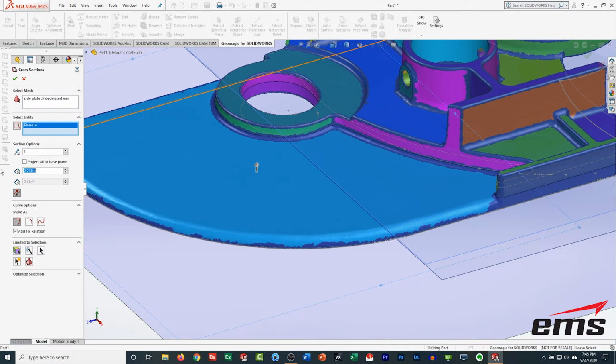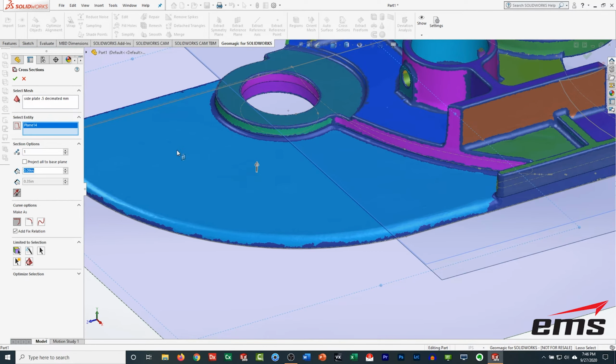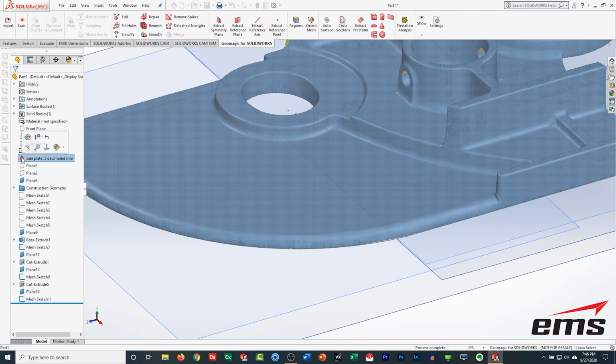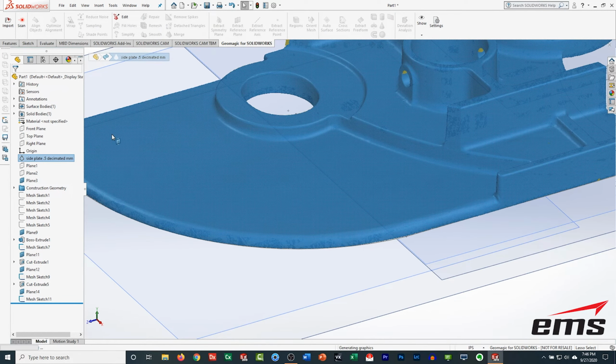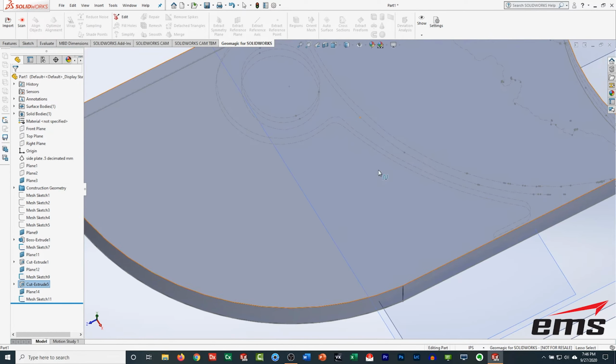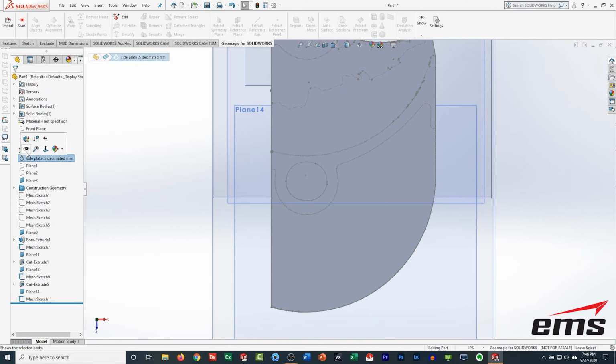We're cutting our section. Again, we want to bump it up. This radius is a little bit bigger, and get it up. You always want to try to get off that radius and get on that vertical wall, or away from that radius. This wall has a little bit of draft to it, but close enough. So we're going to go ahead and build that feature and then just cut that out, just like we did before.